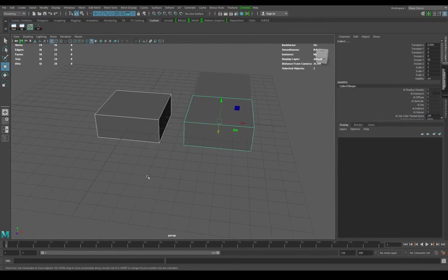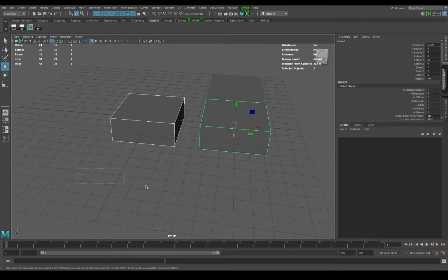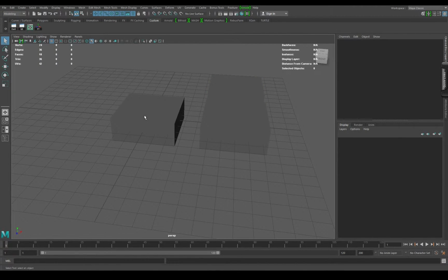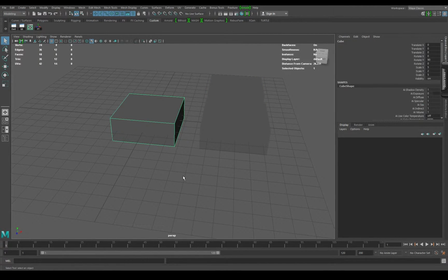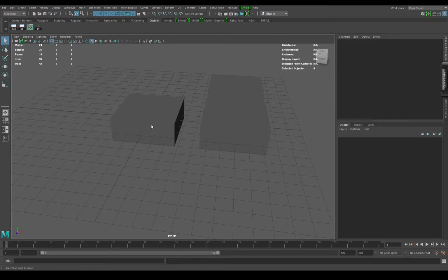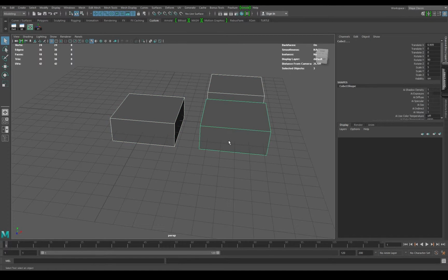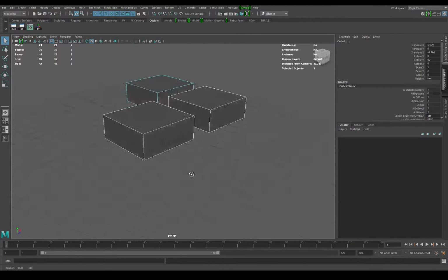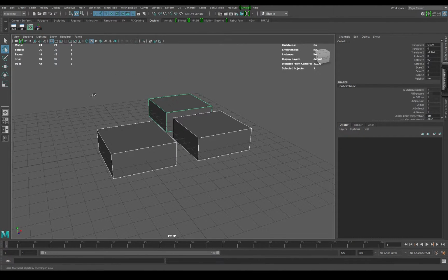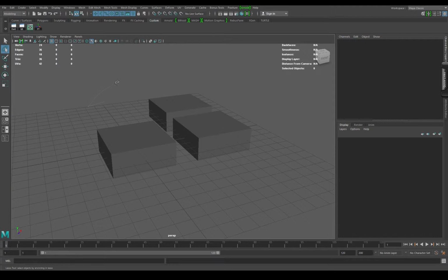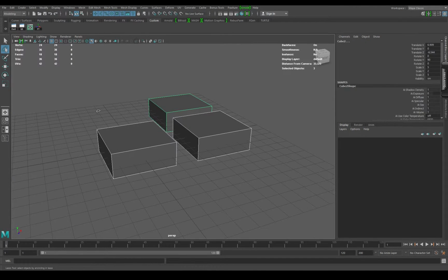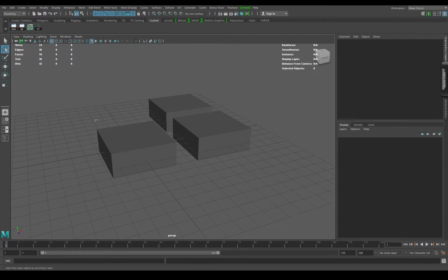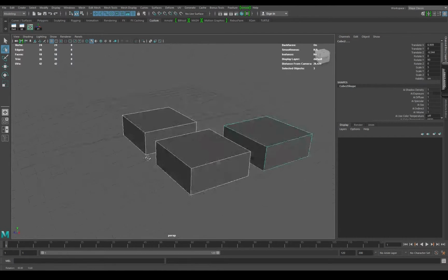If I select 2, so the select tool here or any other tool, I can just select. This tool here doesn't do anything else but select really. So if I click on that one and I want to select another one, I can hold down Shift and click on as many objects as I want to. Or I can grab a marquee around them. This one over here is a marquee select tool. You're not going to really use it for something this small, but if you had thousands of pieces of geometry, or mainly vertices or faces, which we'll get to later, this is when you start using a marquee tool. I can just grab a marquee around the things I want and I can select them all.